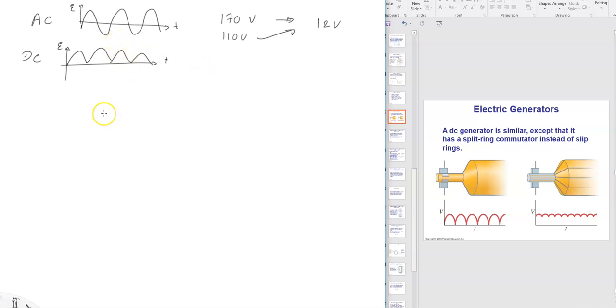The other thing is, the DC that comes out from the generator, we saw in the diagram to the right on the PowerPoint, is an overlap of multiple waves, so it's something like this. Even these little ripples, we can straighten them out and make it a very nice uniform DC voltage by using some electrical components that we have studied before. The capacitor.